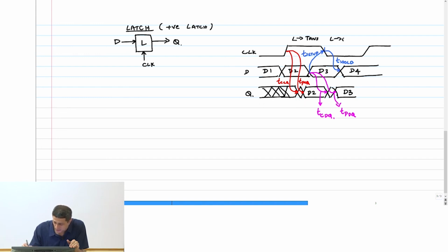Latch is opaque. Right? And the change in D4 therefore is lost. And after you come here, now again the latch becomes transparent. D4 is now still held. Therefore, at this edge, you will have a change causing D4 to eventually appear.